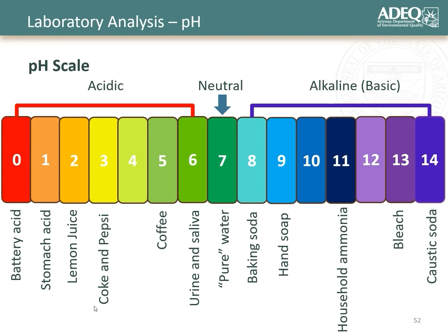Now, pH, as I mentioned before, is frequently a discharge limit for your wastewater treatment plant. And each plant is different, but typically a range between 6 to 9 is a typical discharge range. Once again, every facility is different, and your pH discharge limit for your wastewater treatment plant may be different than that. But that is a standard range. We're trying to keep near neutral and not going too alkaline or too acidic.